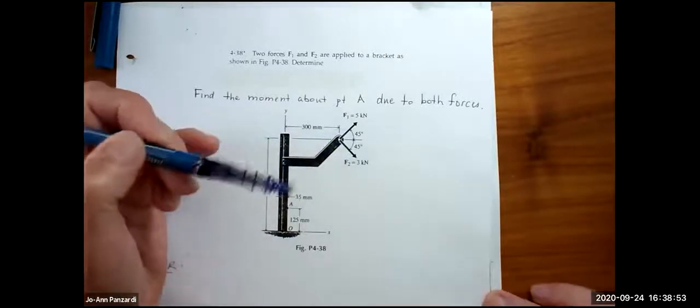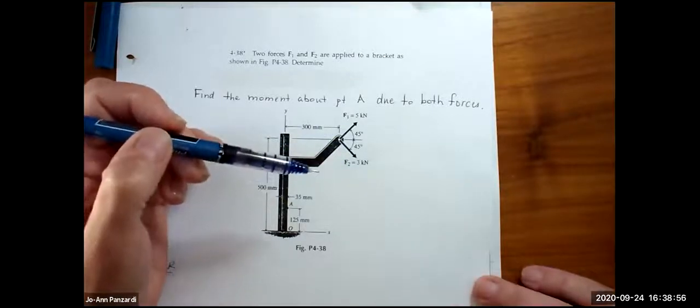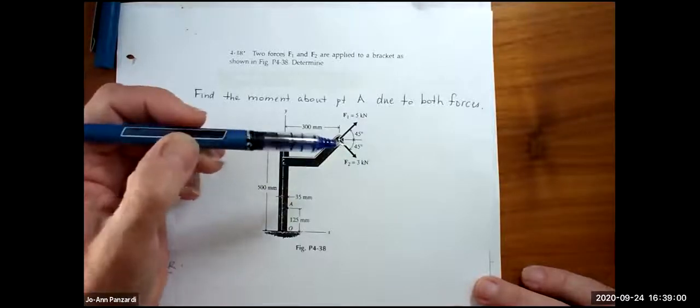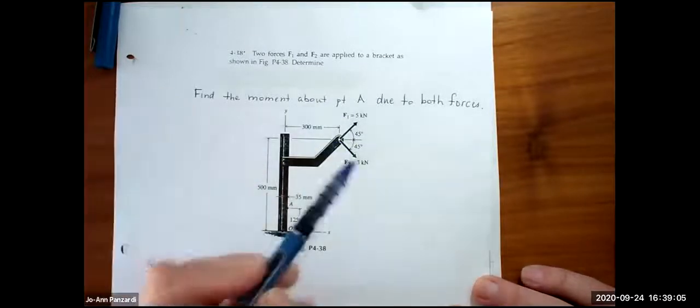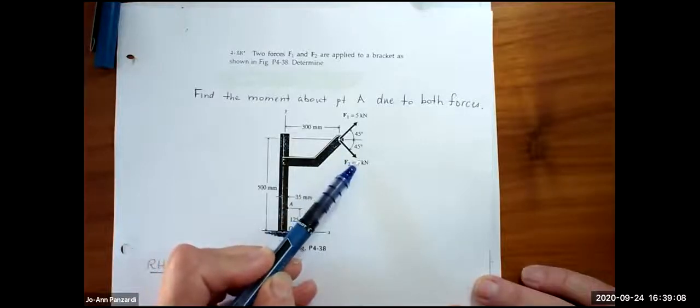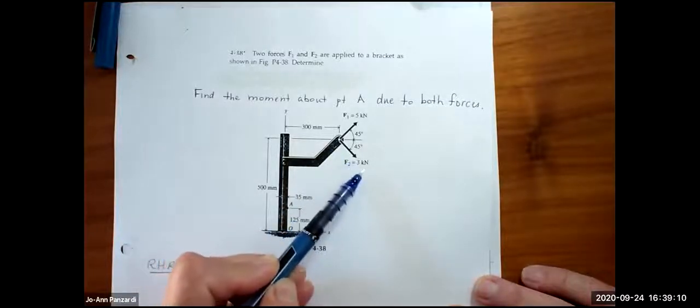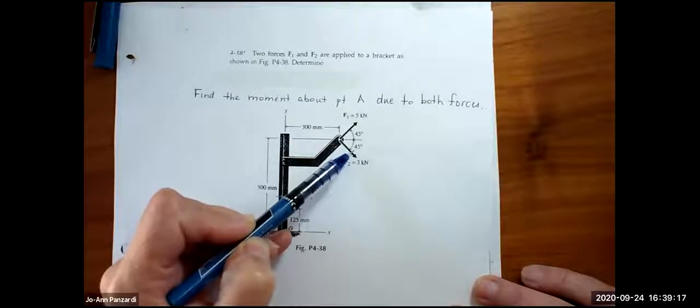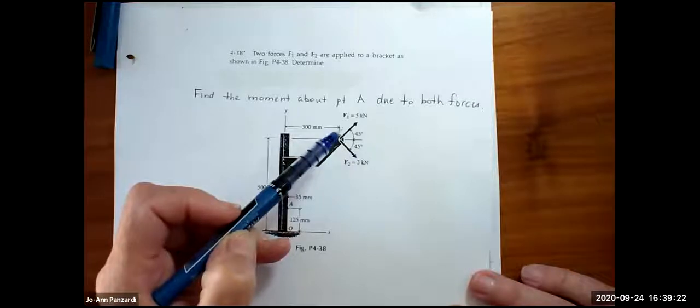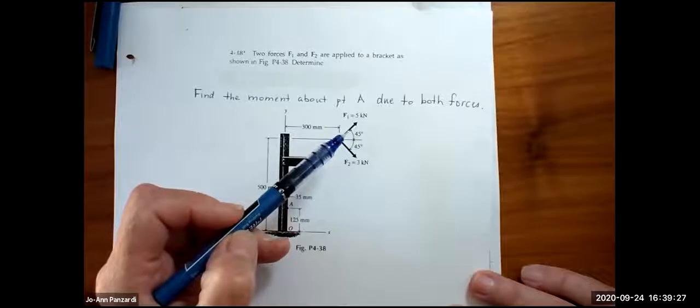When I'm grading, I'm still looking at your free body diagrams because those are so important in statics. Sometimes you're still leaving out the direction of the force. Everyone shows the arrow, and writes the variable or numerical value of the force, but many times you leave out the direction, which can be written in angle form or in distances. Particularly with the 3D problems, don't get sloppy. Those take a long time to draw, and you have to draw them clearly.